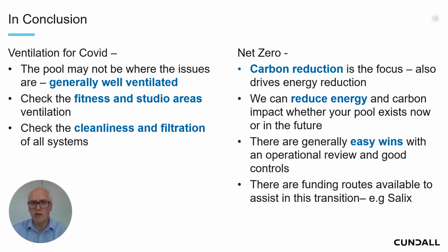So in conclusion, on Kevin's part of the talk, we're saying in ventilation and COVID in pools, the pool hall may not be where the issue is because these are generally well ventilated. We'd ask people to look at their fitness and studio areas to check that there's actually mechanical ventilation and not just cooling in those areas. And for all areas, check the cleanliness and filtration of your systems.